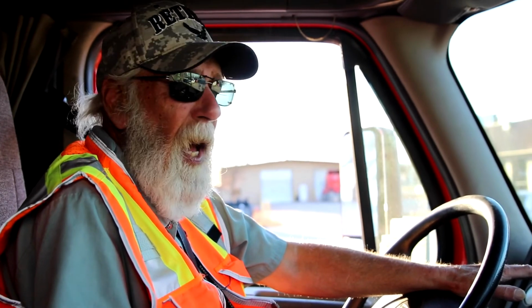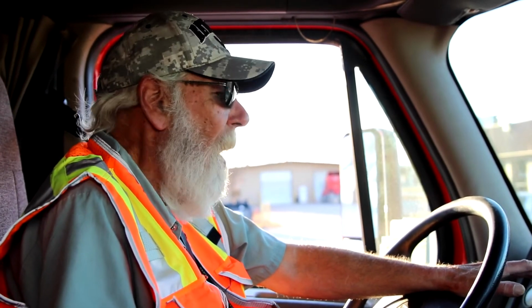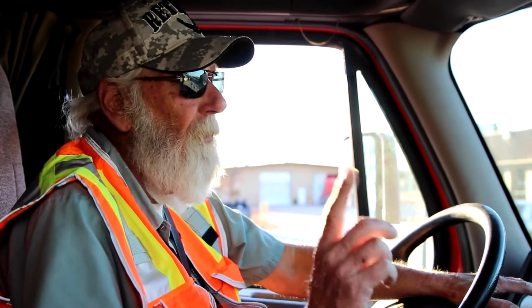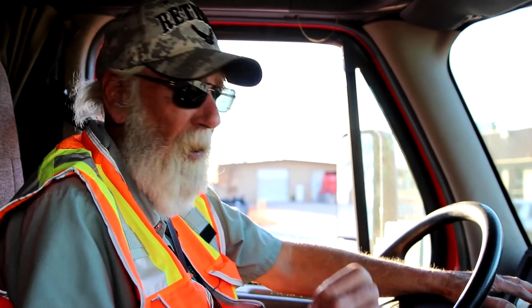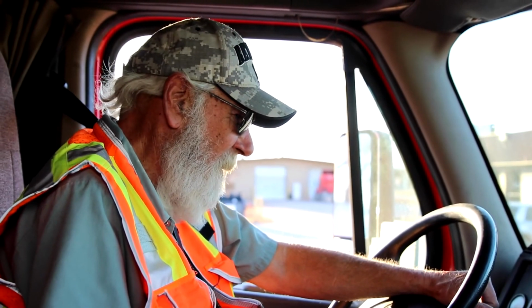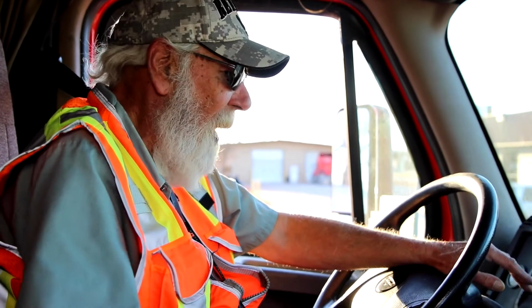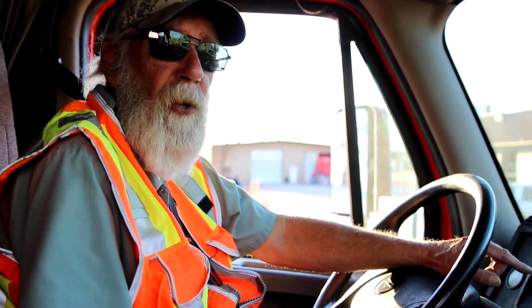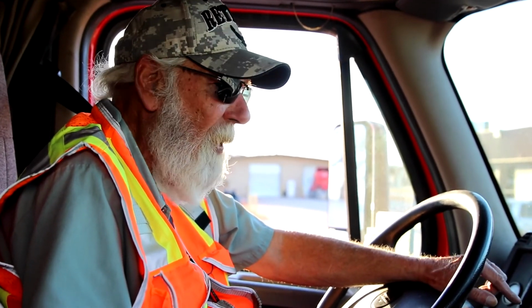Now, as a courtesy, I usually tell the examiner my low air pressure warning light went off at 60 psi, but you don't have to do that, but I do it as a courtesy. We're continuing for the governor cutout between 120 and 140 pounds. You heard that shh? That is the governor turning off the compressor. I'm at 140 pounds of air pressure, both in my primary and secondary air tanks.